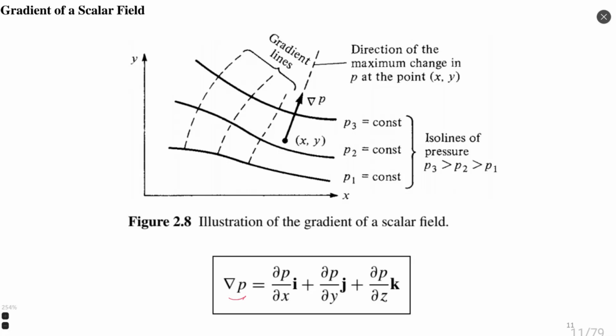For example, any scalar property can be shown as constant level lines. Such a representation we will study in further discussion of aerodynamics. These isolines are a very nice way to show the distribution of scalar parameters in the computational domain. For example, to show the distribution of pressure around an airfoil, Fluent uses the definition of isolines and plots these isolines and fills them with different colors. In such a way, we can see in which limits we have each value of pressure.